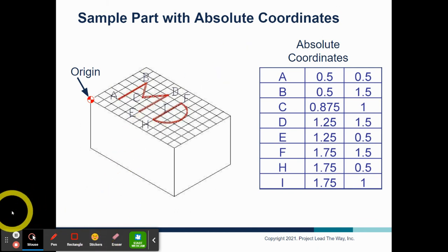All right, so we'll stop here after I talk about this very briefly. This is basically going to be similar to what we're going to do if I can get those CNC machines running. We're going to take a block of material, and then we're going to program this by hand to make your initials. We will have simulation software, and this is actually going to be the next activity you do in class, where you take what you just learned with all the different G and M codes and try to make your own initials. If you have a first, middle, and last name, you're going to do all 3, just good for practice.